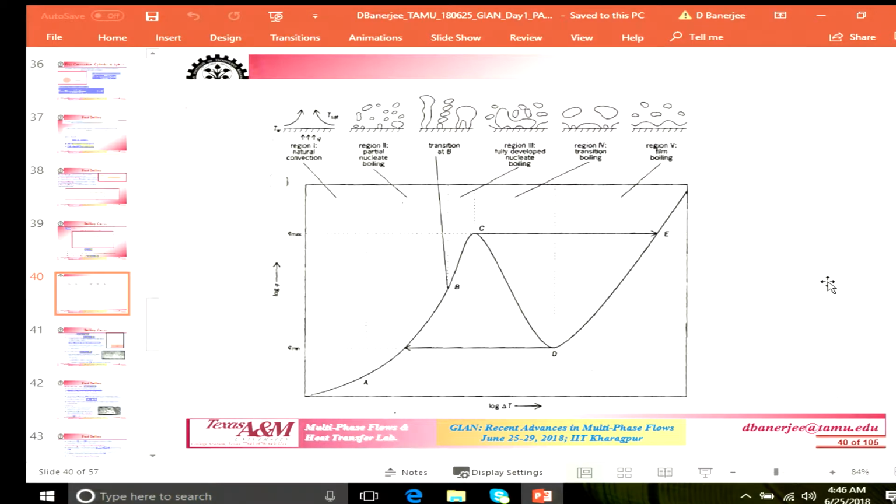Well, when I am over here at the minimum heat flux point, of course, they collapse, and then you get into nucleate boiling once again, or you get into transition boiling, where a part of the heater is in nucleate boiling and then a part of the heater is in film boiling. But when you are in steady film boiling, you expect that vapor blanket to be fairly stable.